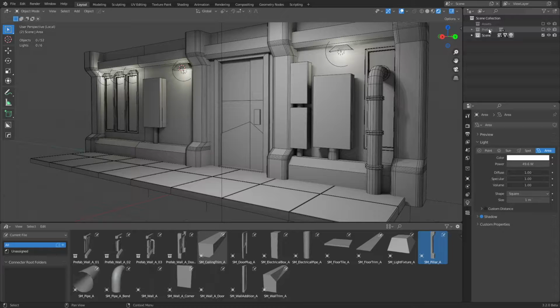For the most part, the more assets you create that look better and line up in a prefab, awesome. This is really the best workflow for this kind of stuff because you're not limited in any way. If you ever need a new prefab, you just create a collection instance duplicate, modify it, and create another prefab, which works. And of course, what we're doing here is the manual way of doing this.